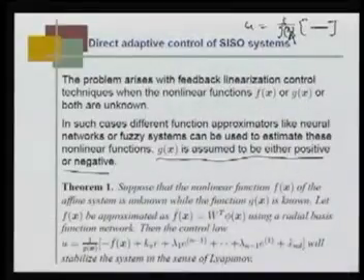Feedback linearization means there will be a term u equal to 1 upon g(x) and some term here. So, if g(x) at some point of time is 0, then the control is undefined, because this is the structure of feedback linearization. So, g(x) cannot be 0. It is either positive or negative, and it has a finite lower bound.